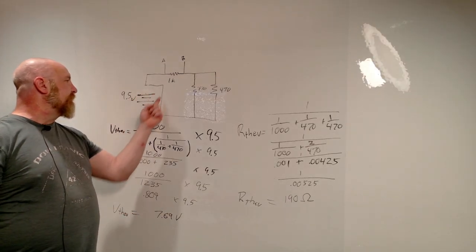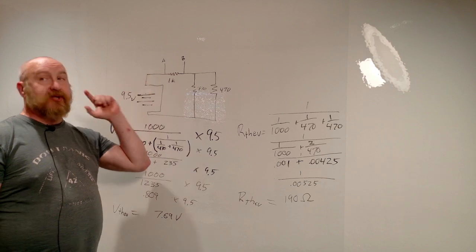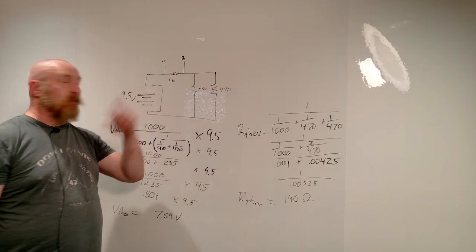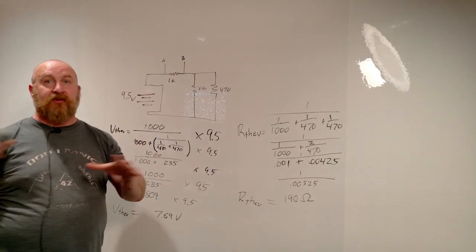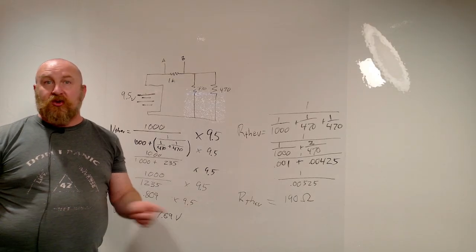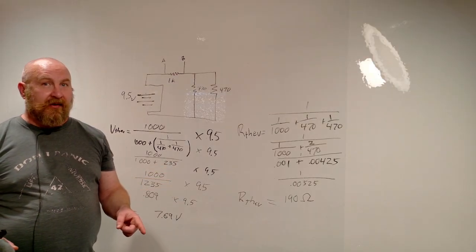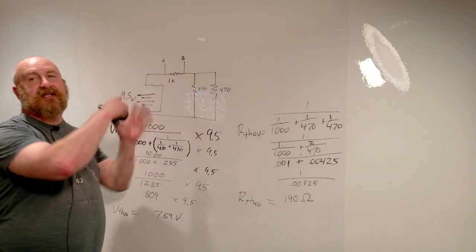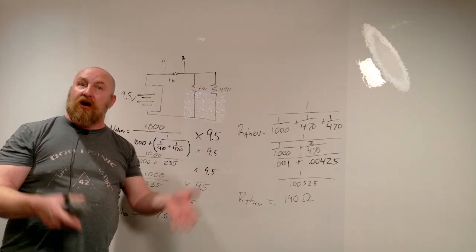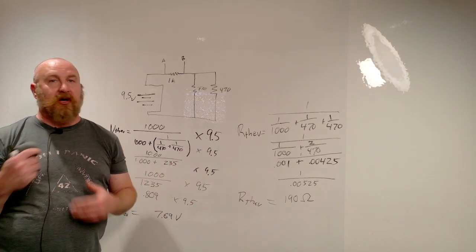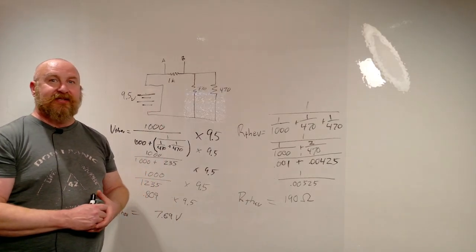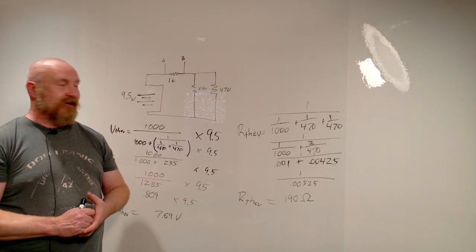And once we jump that wire, it changes the circuit. It changes it so that everything is in parallel in this one. Now, you could come up with a network of resistors. You can plot however many resistors you want on here. You just have to pick 2 points to measure from. And those 2 points determine what's in series and what's in parallel for Vthev, and what's in series and what's in parallel for Rthev. As long as you do the calculations right for adding up voltages and adding up resistances, you're going to be fine in the end.